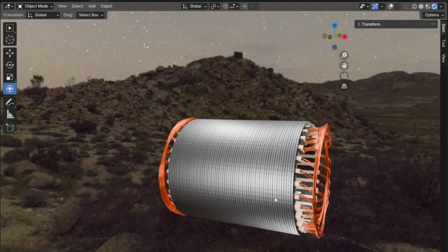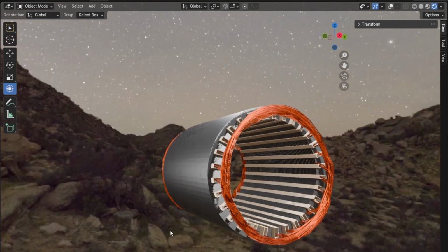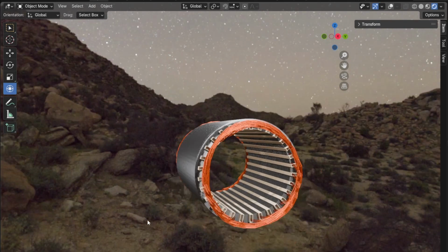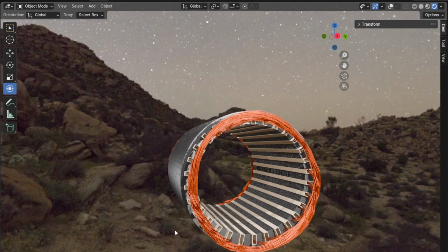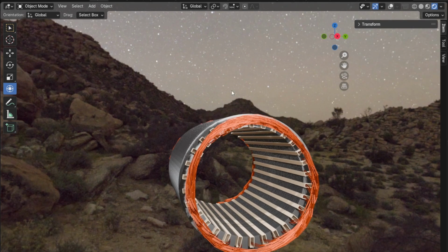So the stator, if you notice, it's got this core material. It's laminated just like a transformer, and it's laminated for the same reason, to break up the crystalline structure to prevent these small eddy currents that can develop within those crystalline structures, and you can end up canceling the fields out somewhat, and it can make the motor not perform as well as it could, and you can get localized heating in those areas as well. So that's why it's laminated, just the same exact reason as a transformer or any other magnetic device like that.